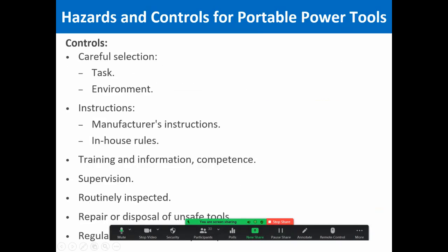What are the controls for power tools? Number one, you should select the power tool very carefully, depending on the task that you are performing and the environment in which you are going to use that power tool. Some sites, such as the oil and gas sector and other high risk areas, do not allow the use of 220-volt tools. So you'll need to select 110-volt tools instead of 220 ones.